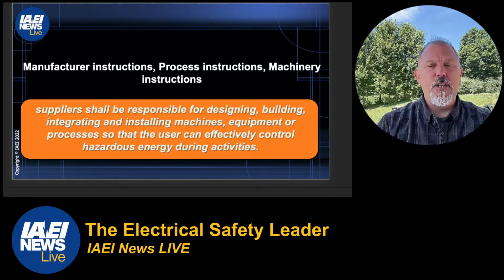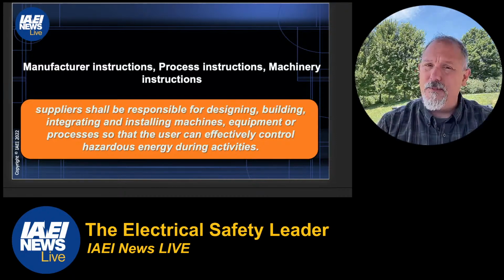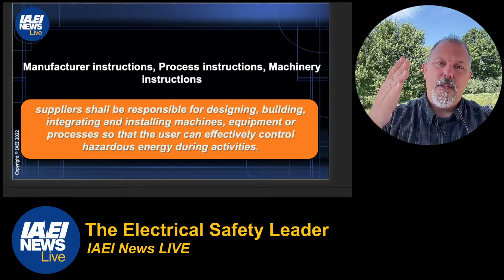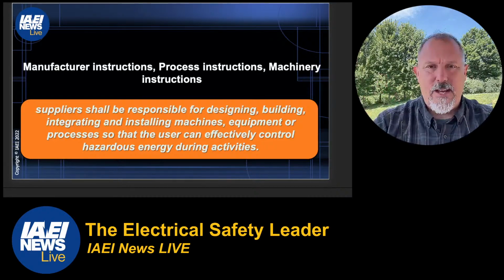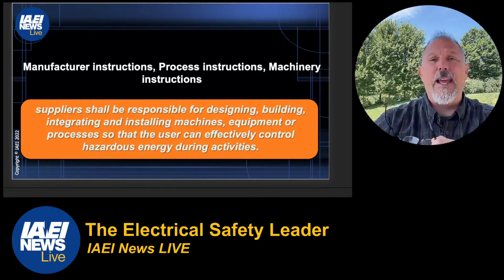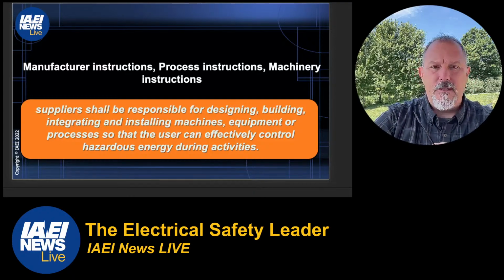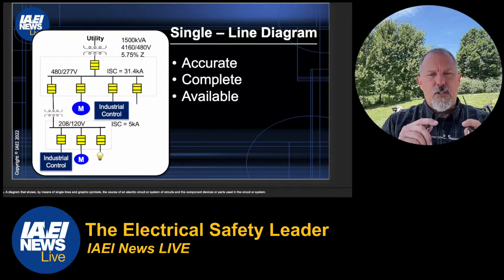You're going to want to look at machinery instructions. A lot of the machinery that your electrical workers, or any worker, uses. Remember, it's not just electrical. In my opinion, there are a lot of other reasons that you need to think about for establishing an electrically safe condition or doing lockout tagout. It might not be just electrically safe. It could be a mechanically safe working condition. Lockout tagout is used for many different things. But a lot of information is coming from manufacturers of the equipment or the process.